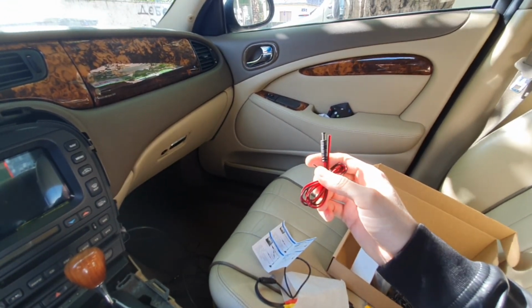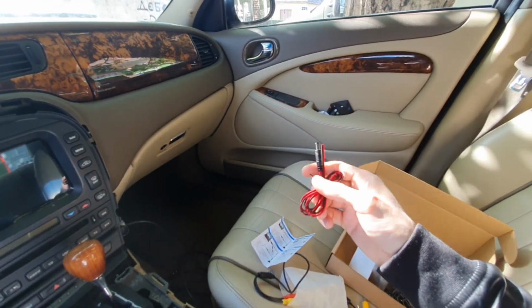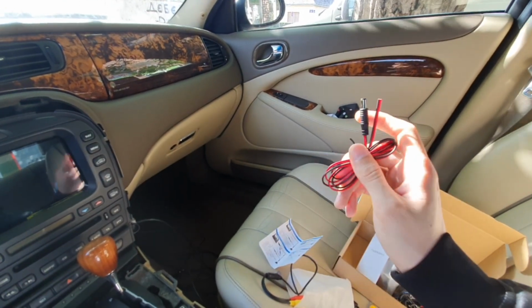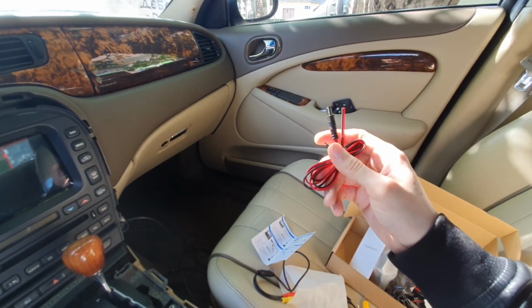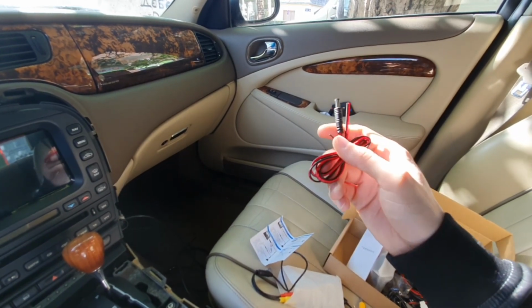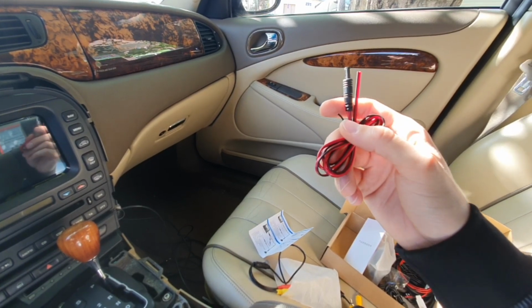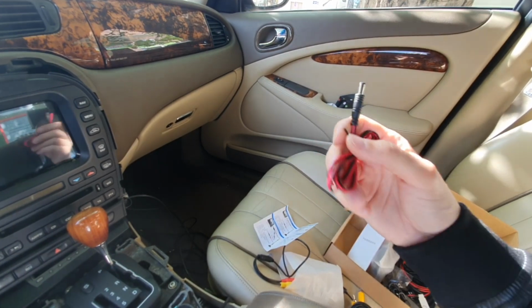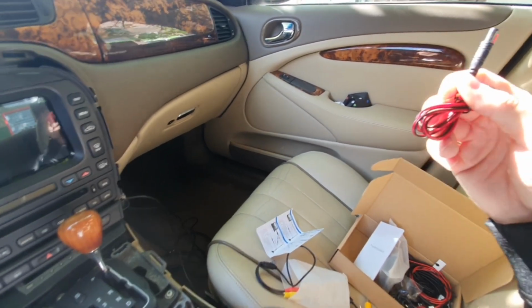There is an option actually. If you find a cable that is powered up only on ignition, like any other module in the trunk, like parking aid or something like that, then you will be able to switch to the camera even not in reverse and see what's behind you while driving. I'll show in a moment how to do that.